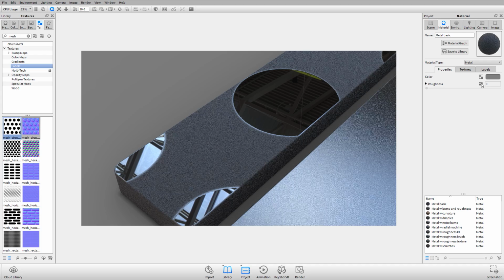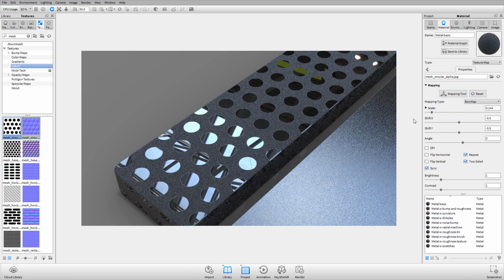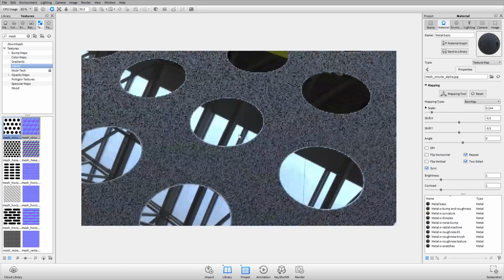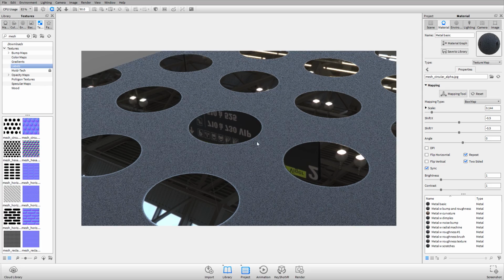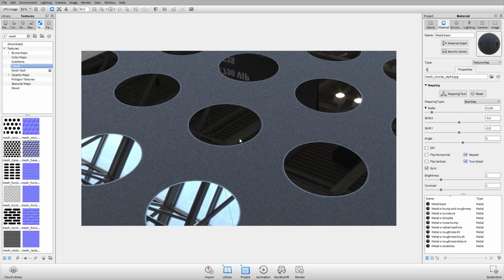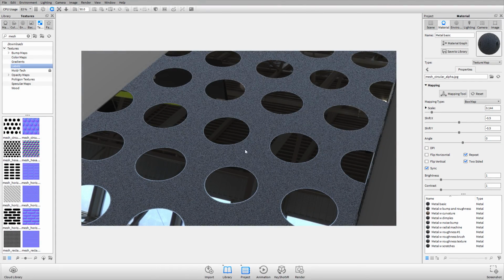Right? And now take a look at my surface, and I'll click on that texture and I'll scale it down a little bit. What roughness textures do, it's like an in-mold kind of pattern. It's saying that wherever our image is black, we have a roughness of 0. Glossy, smooth, perfect. Wherever our image is white, we have a roughness value of 1, which is super rough, right? We're getting more of a matte reflection. And this is very different than a specular texture. A specular texture controls the reflectivity. What we're doing here is we're controlling the roughness.